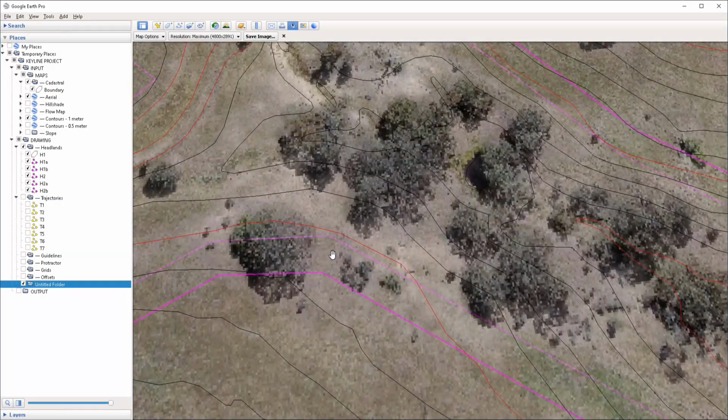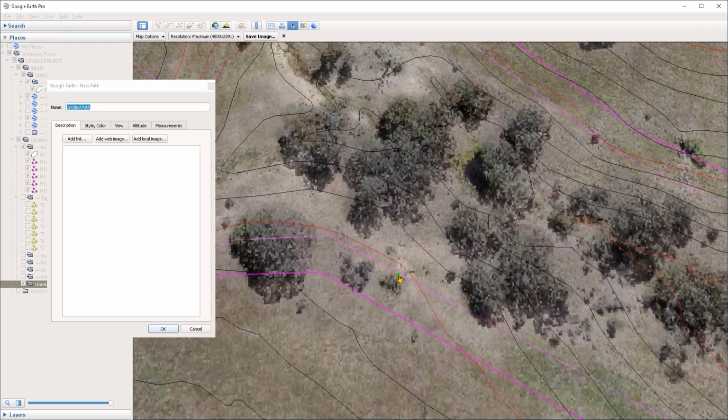Now, something that I completely forgot when I was creating the extensions is that you should never make the extensions out from the angle where the line is breaking. The extensions should always be made from the segments in between the points. This is because if you make an extension from an angle, then the extension is not going to give you the 10-meter width in between the segments, because an extension made from an angle is either going to be shorter or longer than the one that you actually need. So when you're creating these extensions as guidelines, always make them out from in between the straight segments.